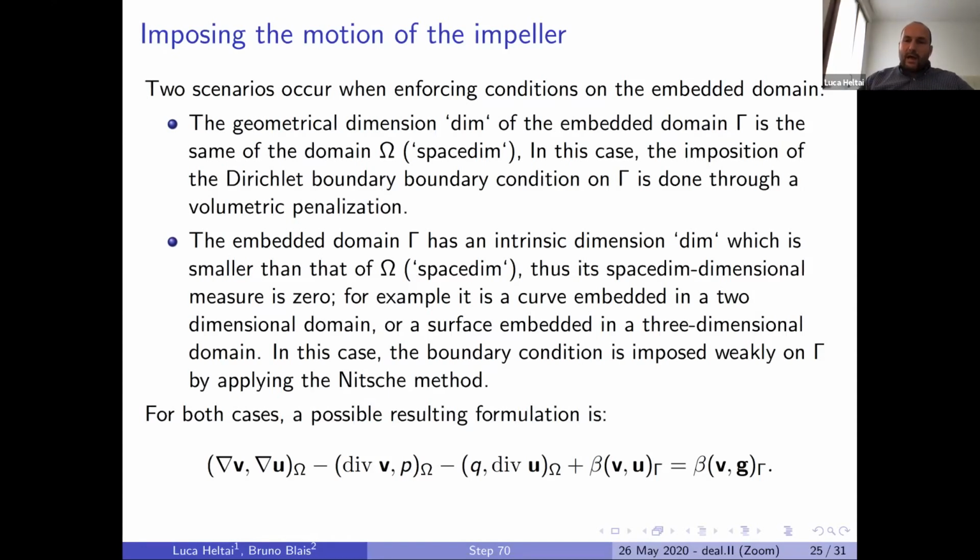So you somehow have to keep track of the positions of the solid domain, but only of the basis function values of the test functions on the fluid domain at the reference positions of the solid domain. And this is where the particle handler comes in very handy.